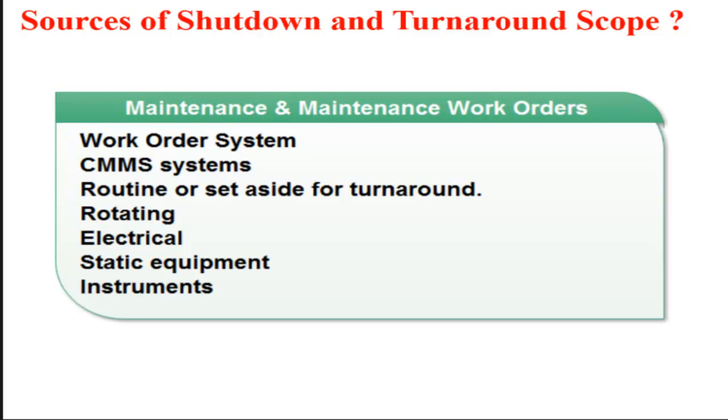So we have to decide whether this work order can be designated as routine maintenance, and then it has to be done during operation or while running, or whether it has to be set aside or kept for later on, to be included within the maintenance work orders for shutdown and turnaround scope.